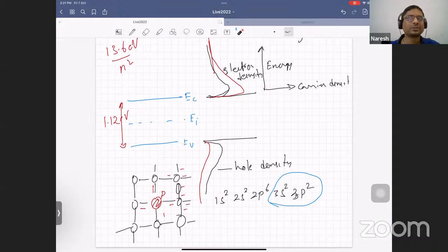But if you are preparing a substrate, silicon is prepared by melting, I think I mentioned it somewhere in the course. We melt sand, it goes through a process and is purified. And in that process, you add a tiny amount of phosphorus. Then it gives you doping.